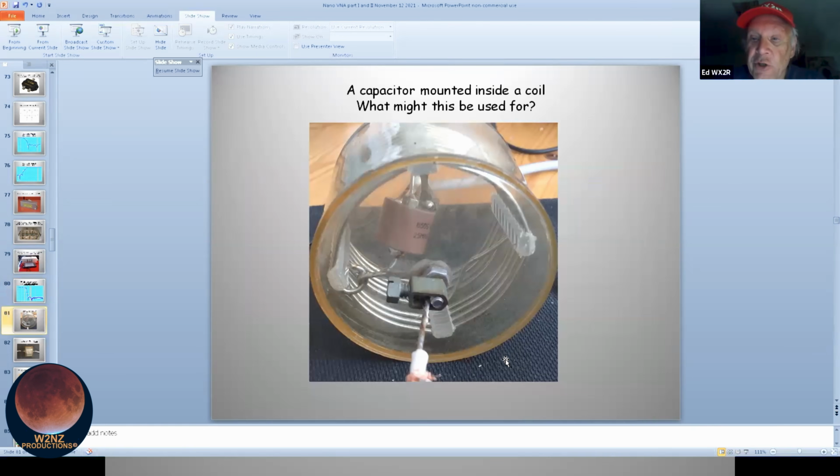Hey, Barry, we've got a question here from Bill, WA2WL. Can you measure all 4 S parameters, is his question. Oh. I'll have to try that. That's a very good question. I see no reason why not. See, S11 means going out 1 and coming back 1. S21 means going out 1, coming in 2. Oh, the answer is no, because it's only one port transmitting and the other port's totally receiving.